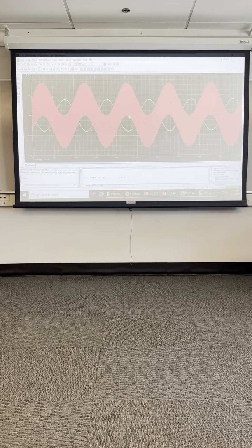This is V in, it contains 100 hertz and the 30 kilohertz. That's why it has this kind of fuzzy on it. V out is only the 100 hertz component. And it's approximately 3.2 of V in, because the 30 kilohertz is adding to the 100 hertz. V in peak to peak is different from V out. So this is something like your second one.